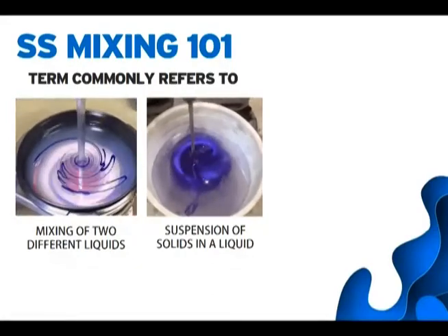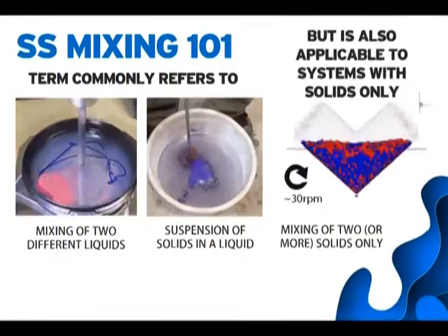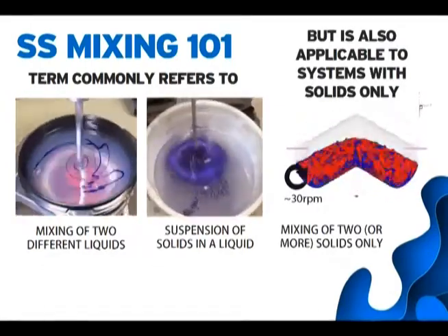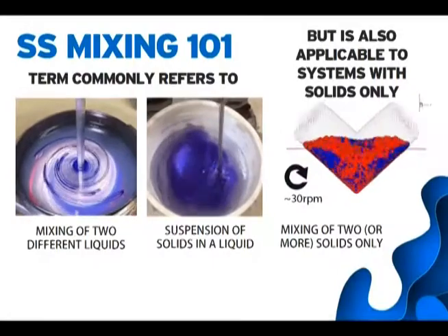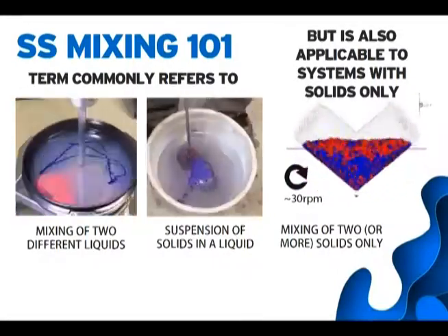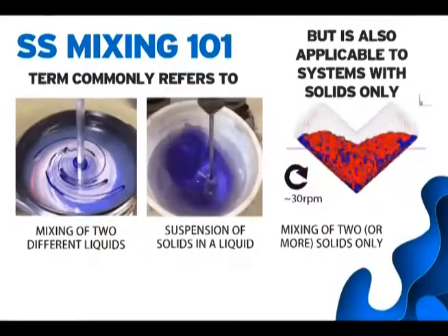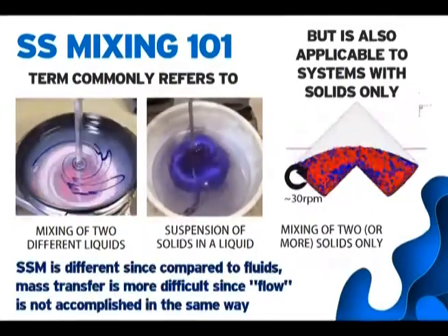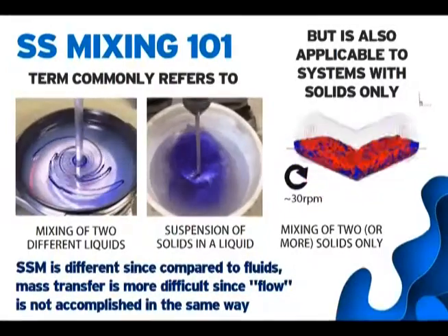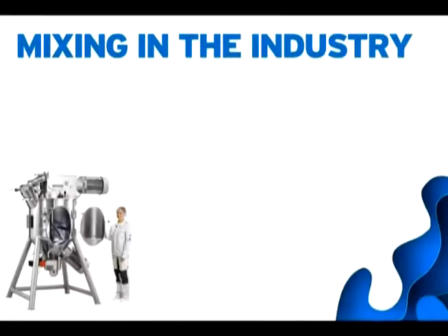This is often done by subdivision and blending of separate fluids so that microscopic diffusion will lead to homogeneity. However, mixing can also apply to solids. Solid-solid mixing is a unit operation widely used in manufacturing, in which two or more solids are treated so that each solid particle lies as nearly as possible in contact with a solid particle of each of the other ingredients.